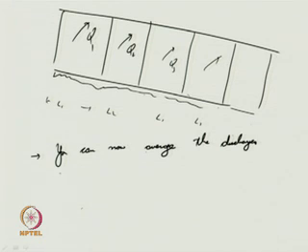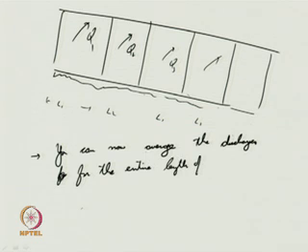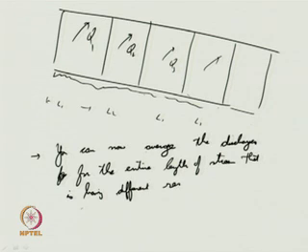You can average the discharges for the entire length of stream that has different reaches. Like this you can sum them for the entire stream, average them, and get the average discharge for the entire natural stream. That is the way you can compute. You can use appropriate weights also to compute the discharge.